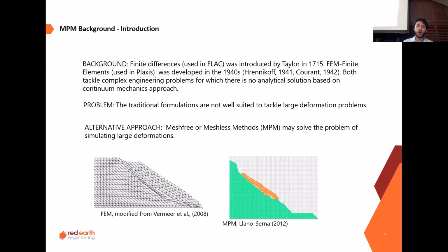Both of them are used to tackle complex engineering problems for which there is no analytical solution, based on a continuum mechanics approach. So there is a problem there, because the traditional formulations that we have already established are not well suited to tackle large deformation problems. And this is again talking from a geotechnical engineering perspective. So the alternative approach is to use mesh-free or meshless methods, which MPM fits within. And these methods can solve the problem of simulating large deformations.